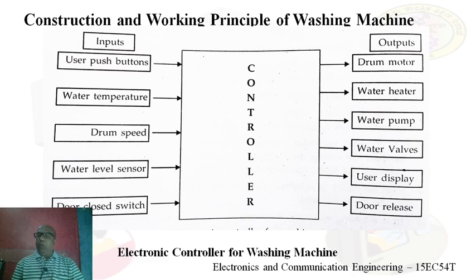In the top loading machine, the agitator twists back and forth in clockwise and anti-clockwise direction and pulls the clothes down to the bottom of the tub. The clothes work their way back up to the top of the tub, where the agitator grabs them again and repeats the mechanism continuously.